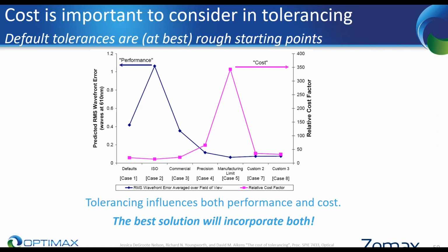So a summary, as I can conclude today, of a few of the cost drivers. Cosmetic tolerance, your scratch-dig, is a huge cost driver, especially once it's below 60/40. Small clear aperture relative to the diameter is challenging from a number of different perspectives, and can add cost, as well as a tight radius and irregularity. A chemically stable material may have lower optical performance, but the fabrication may be cheaper. And high aspect ratios, thin edges, and exotic perimeters are possible but costly.